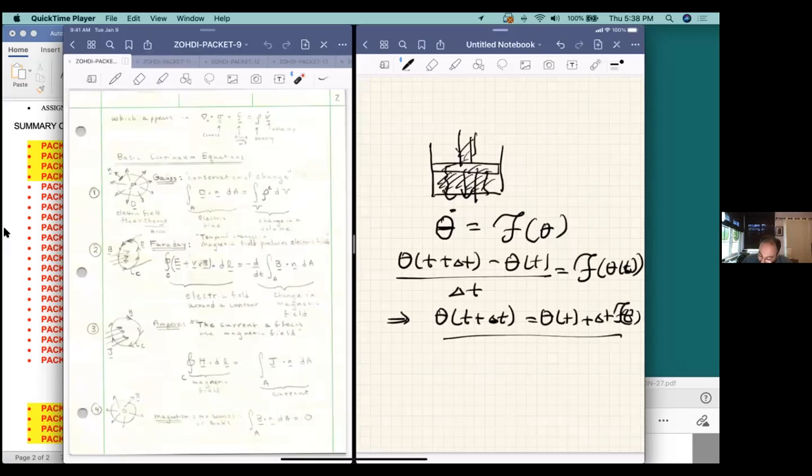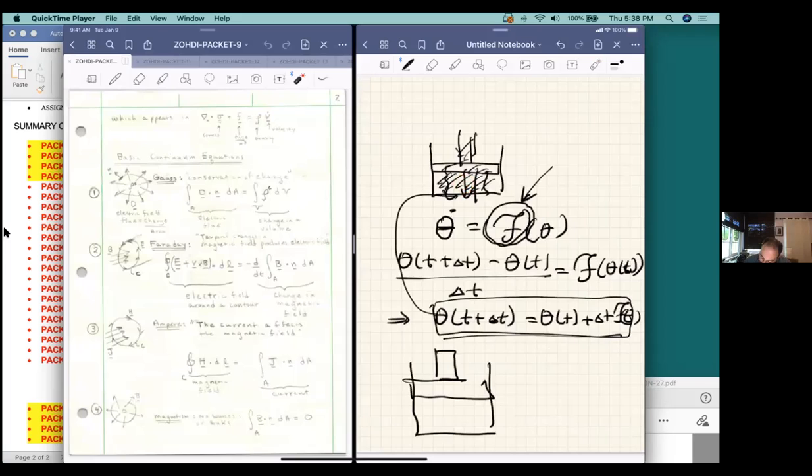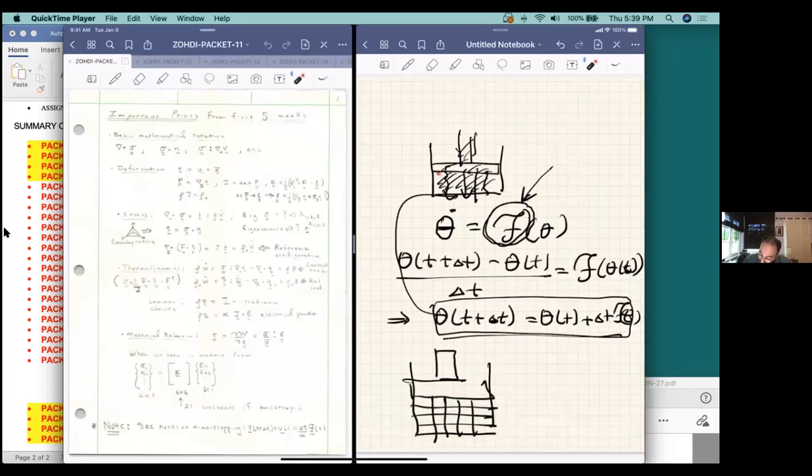Of course, to get to whatever this monster is in your assignment, I derived it for you in the notes. In the actual assignment itself, f can be something horrifically complicated, but at the end of the day, you're faced with only solving an ODE for the value of the temperature inside of this blob, versus the nightmarish problem of taking this thing and discretizing it with some type of finite element method. So you could, of course, do that and put a grid on this rascal and then solve the equation where all of the different pieces of material are heated up through solving that partial differential equation. Not an easy task, I have to say. The problem is relatively beastly. However, again, the first law of thermodynamics can be reduced, and you can get a pretty good approximate model that you can get away with for most design analyses instead of going after this monster.